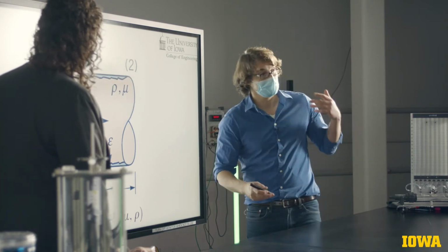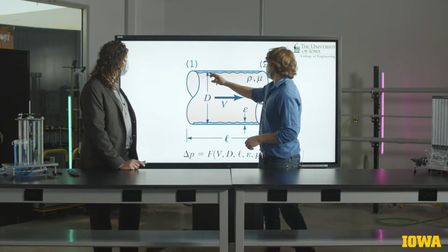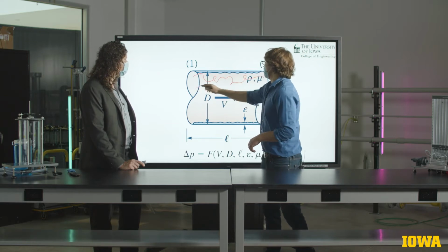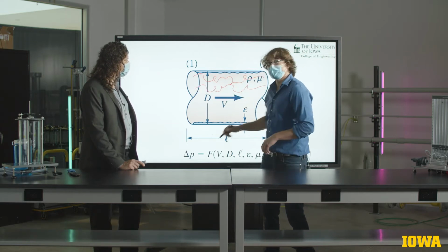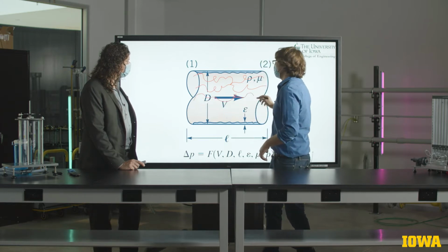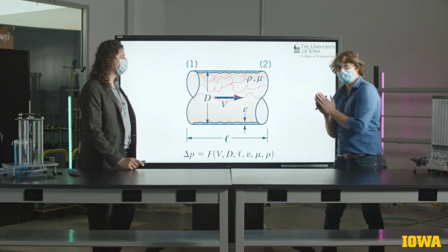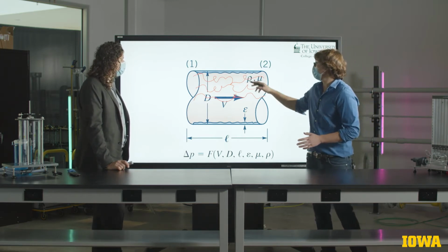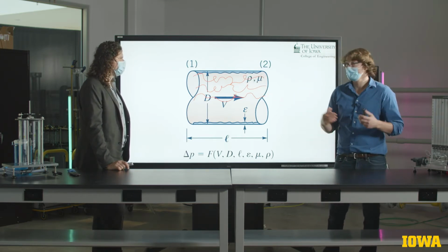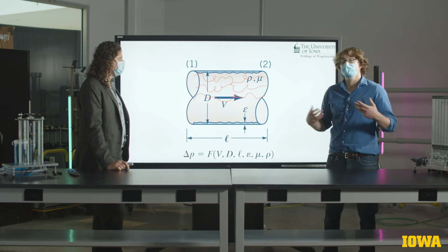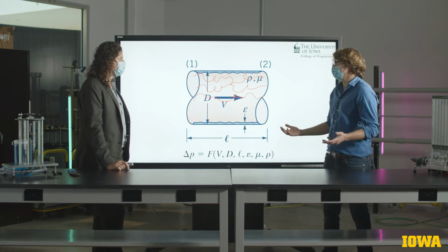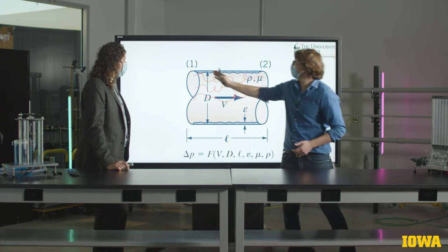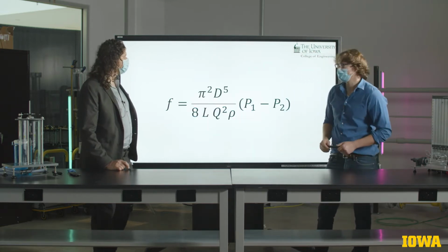And we'll see through the measurements in this lab that the product of added roughness in the pipe is to induce extra tortuosity or turbulence in the flow that creates a lot of intermolecular friction between the different fluid particles, as well as between the flow and the walls of the pipe. All of this amounts to more heat and therefore more energy loss, which means that the pressure drop between point 2 and point 1 will be increased.